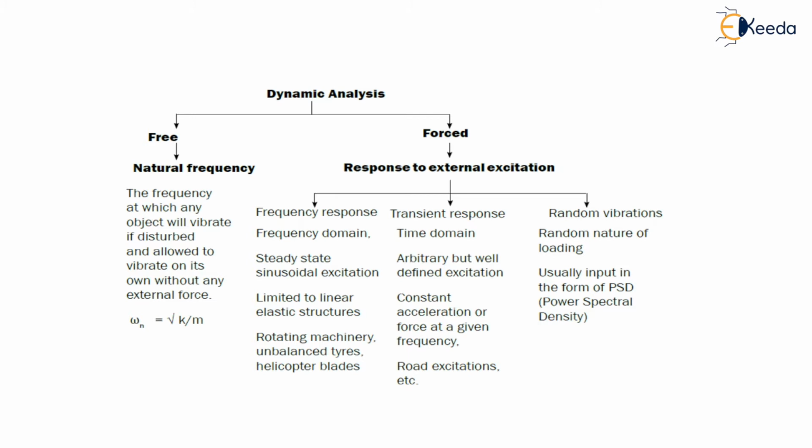Response to external excitation has three types of analysis: the first is frequency response analysis, the second is transient response analysis, and the third is random vibration. Frequency response is the frequency domain, related to steady state or sinusoidal excitation. The waves are in sinusoidal form, and it is limited to linear elastic structures only. Rotating machinery, unbalanced tires and helicopter blades are considered in the frequency response domain.